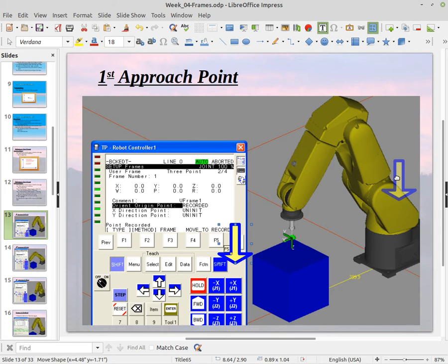And as I said before, all points are measured on the tool center point. Remember this green ball here in the RoboGuide software is referred to as the TCP globe, the tool center point. And so all points are truly measured from here, which is the origin, out in the X direction, up or down in the Z direction, and left or right in the Y direction to that tool center point. So all points are defined from the origin to this tool center point.